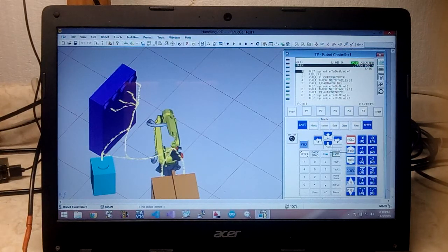And it's the same case for the load machine. Load machine down here is a program to which I pass down a register. This register starts with a value of 1, and that value is incremented after the part is offloaded. So once the part is offloaded into the conveyor, placed here, the spindle count goes up by 1. And if the count is greater than 4, then the program exits or terminates. It goes to label 2, which then terminates the program. But as long as the count is less than 4, it will go back to label 1. So this program will complete a 4 spindle cycle.